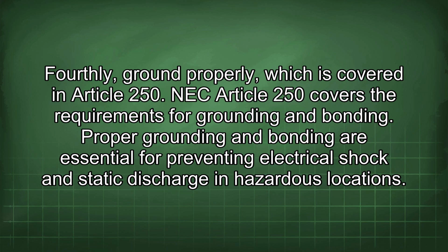Fourthly, ground properly, which is covered in Article 250. NEC Article 250 covers the requirements for grounding and bonding. Proper grounding and bonding are essential for preventing electrical shock and static discharge in hazardous locations.